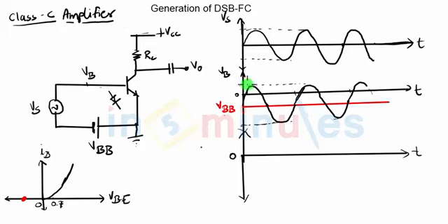So you can now see that the resulting voltage at the base remains below zero most of the times, except when the sinusoidal signal takes its peak values. Those peak values are good enough to be above the zero level, because those positive peak values, when added to the negative DC supply, the overall base voltage, the overall VB, is positive. The base emitter will be forward biased and the BJT will conduct only for these small peaks in which base voltage becomes greater than zero.